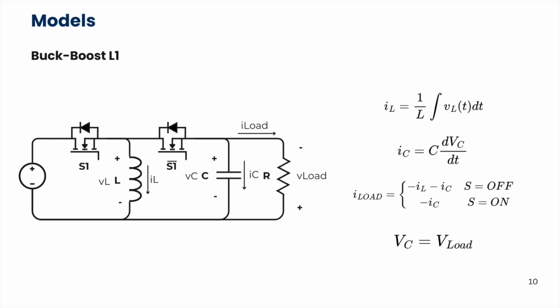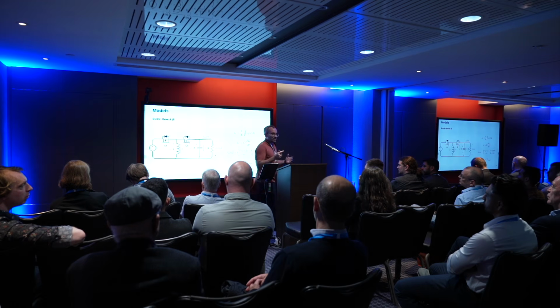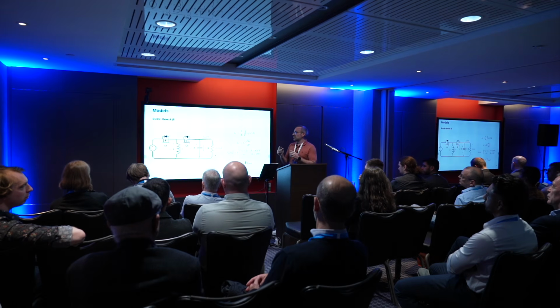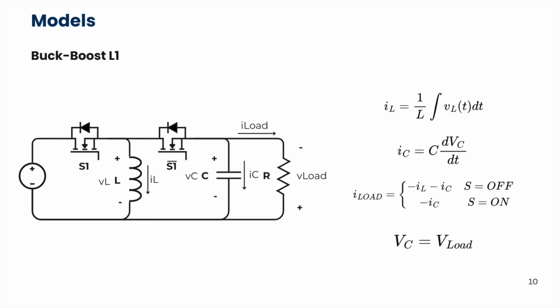The same for the capacitor. Here you can see that the behavior of the capacitor, the current through the capacitor, is a function that depends on the derivative of the voltage that we are going to apply. Then these two switches are being represented using a nonlinear equation. This is the equation that you have here, and finally the voltage of the load is the same as the voltage of the capacitor.